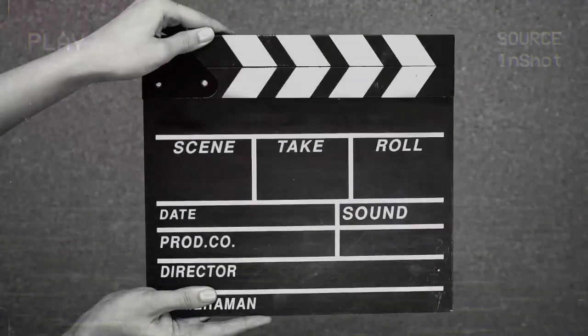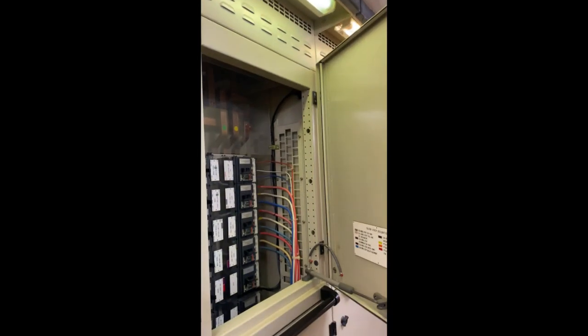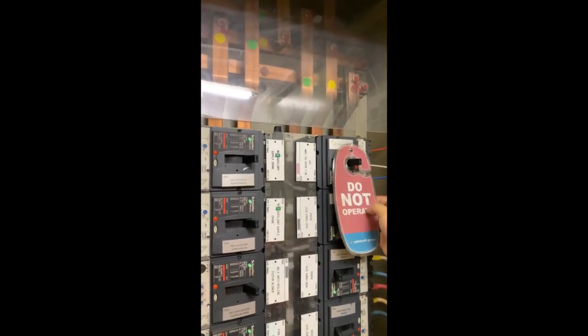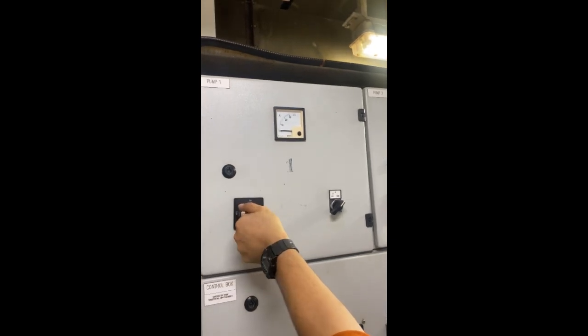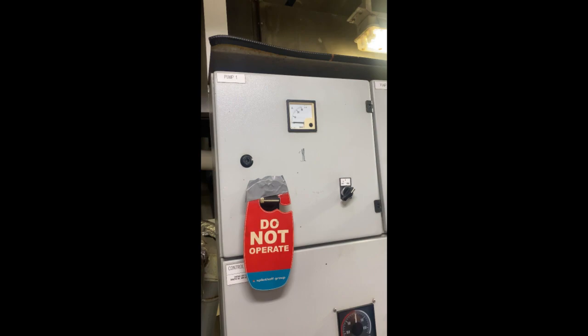Now we start with the overhauling of electric motor of hydraulic pump. Before you start any maintenance, especially electric stuff, make sure to switch off the main breaker and you put a tag on it. If possible, put a padlock. Also put tag on the main starter.